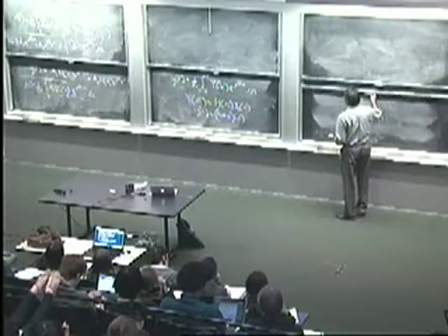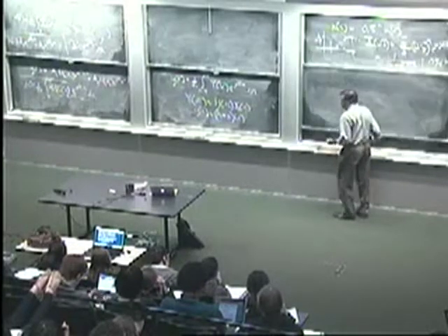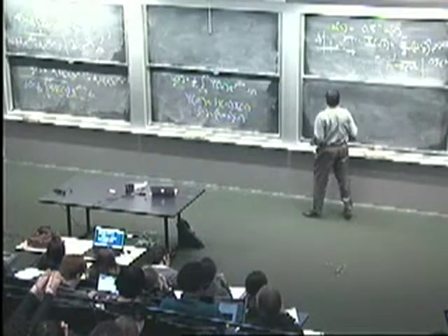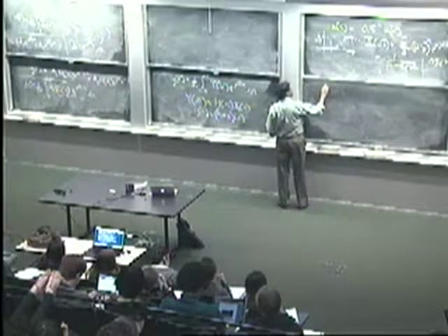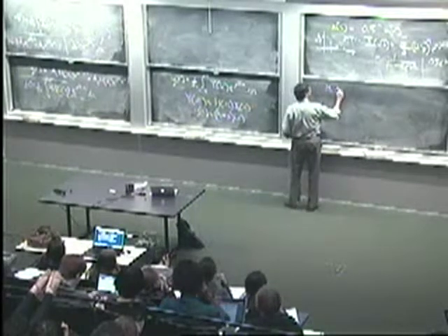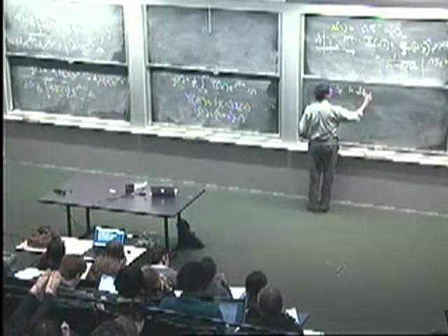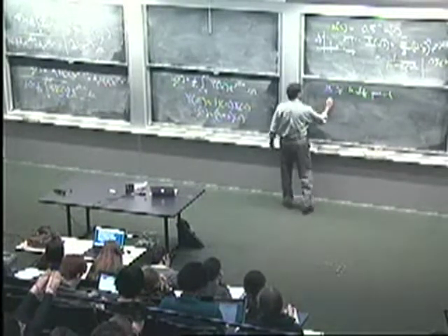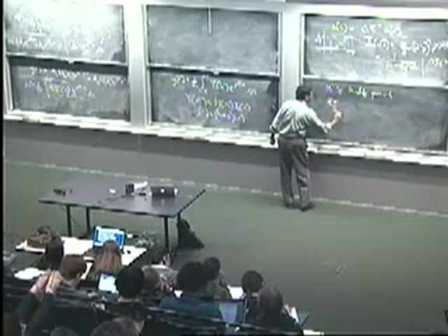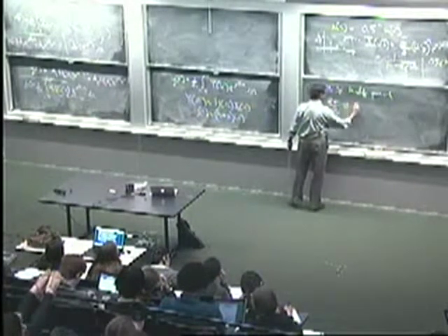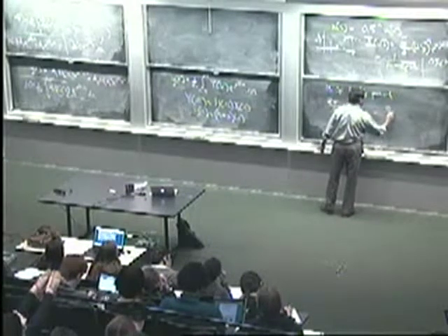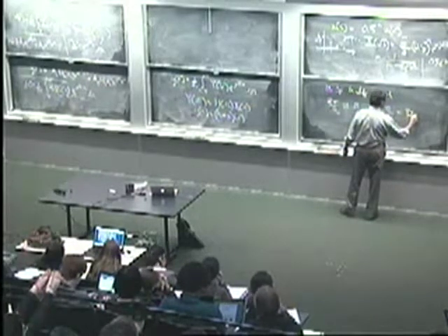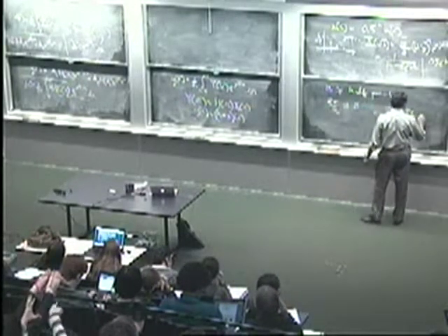these are just rough calculations, but it helps you understand what we mean by spectral content and helps you as a way of checking answers. But let's see, if I said 18 was approximately a half period of an underlying sinusoid, and I don't see anything faster than that. Period is 2 pi over omega naught, so I'm saying that's approximately 18. So the frequency that I expect to see, the fastest frequency there is 2 pi over 18, or pi over 9.